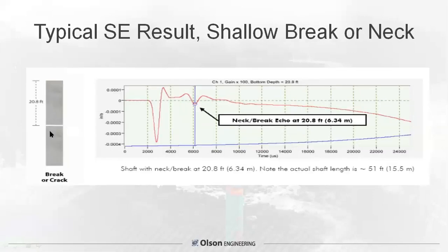Now, if you have a shaft that's broken, you're going to get an echo, the same type of echo you would from a short shaft. You can't tell a short shaft from a broken shaft unless you know how deep the shaft is supposed to be. That kind of makes sense. But it will definitely show the depth, the effective depth of your foundation.